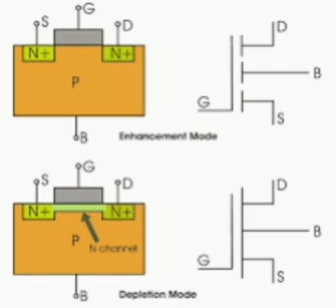Semiconductor devices. Photoconductors. When light falls on semiconductors, their conductivity increases, and this property is called the photoconductive effect. This is also called the photoresistive effect. The minimum photon energy required for intrinsic excitation from VB to CB is the energy gap EG. Extrinsic excitation from the donor level to CB or from VB to the acceptor level requires less energy than the energy gap. The photoconductive equation is given by EG equals h nu equals hc by lambda, where h means Planck's constant, c means speed of light in free space, and lambda means wavelength of light incident on the semiconductor. The wavelength of incident light can be given as lambda equals 1.24 by EG in electron volts.